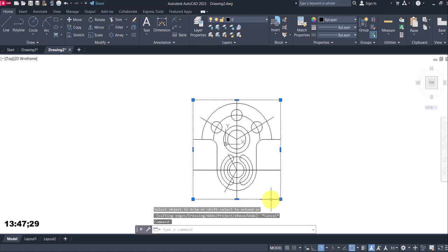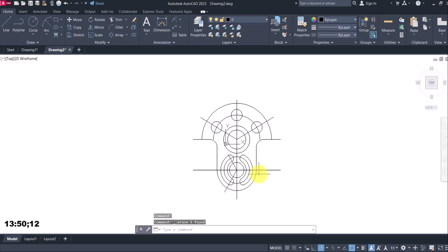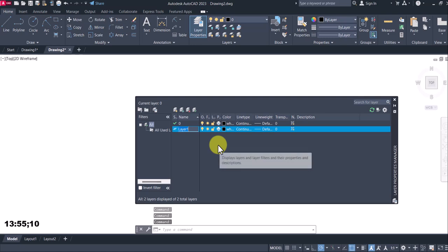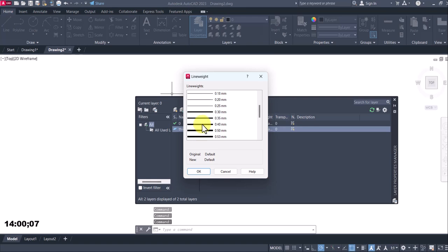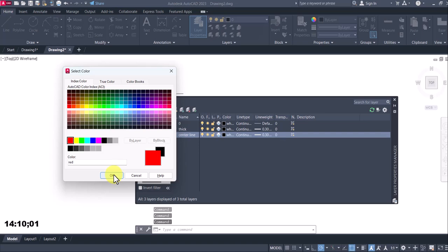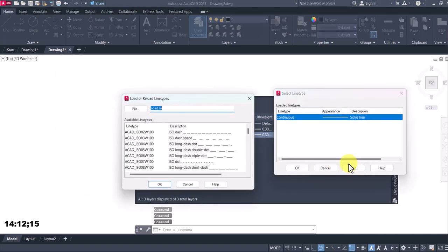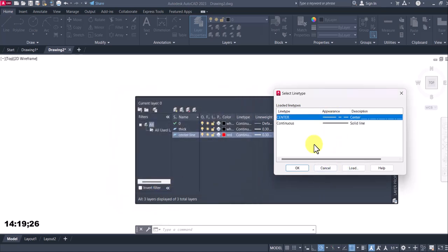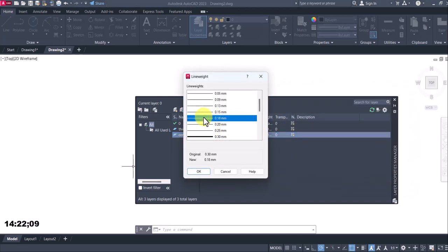Then I can now remove this rectangle I've drawn. Okay, yes. So now let's go to layers. Layers, create. Let me call this tick as usual. Then make the line width tick. Another one, center line, red color. Give it a center line. Find center line for my list. Center line. Okay. Then choose it here. Apply. Then I don't want it to be tick.